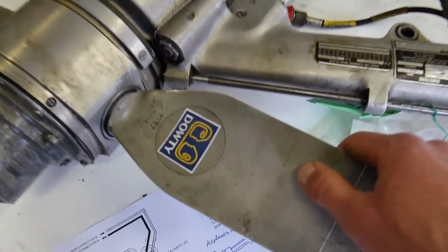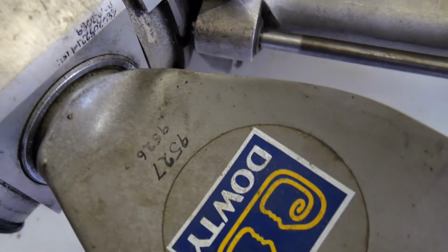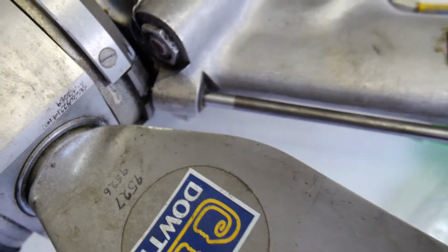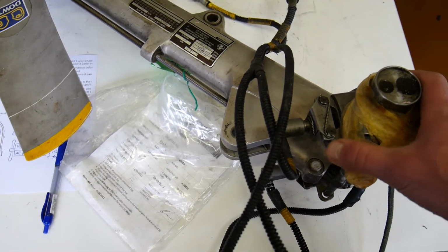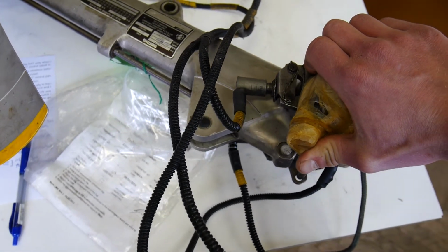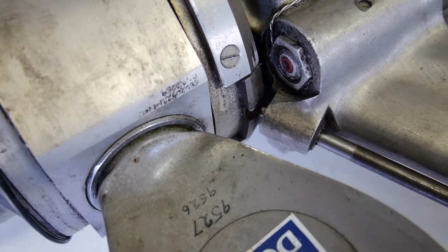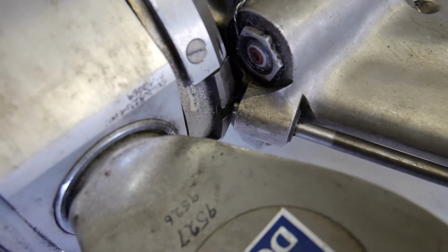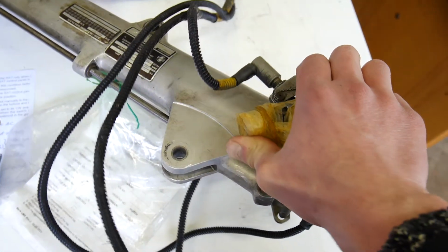On the ground, maintenance personnel will manually rotate it back to the index position, and further, by means of the stowing pump, which is also built into the deployment mechanism, they start to stow it back. After 10 degrees of rotation, the index pin goes back, so you can check that it's fully aligned, and further you can put it back into the fully stowed position.